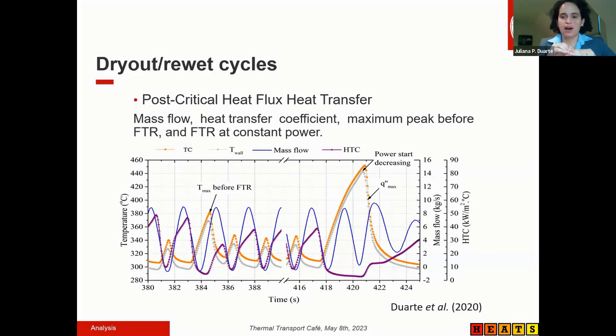For our flow instability analysis, if you wanted to be conservative, at the moment that we have this instability growing, independently of whether you're having these cycles or not, this is the moment that it's not safe anymore, because you can have a mass flow oscillation that will potentially lead to the onset of these oscillations.